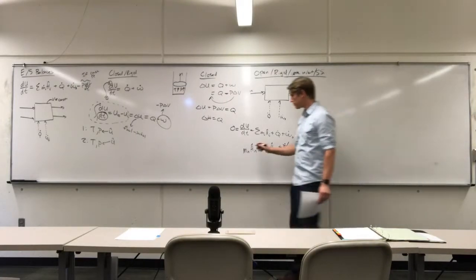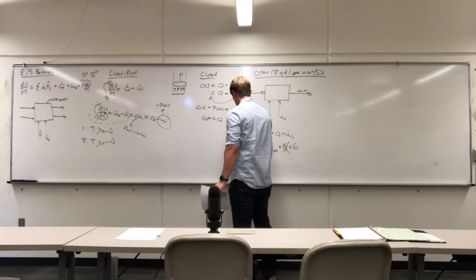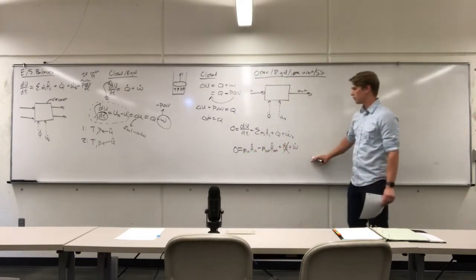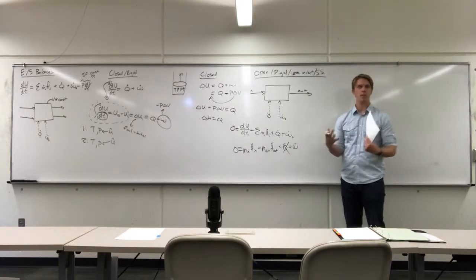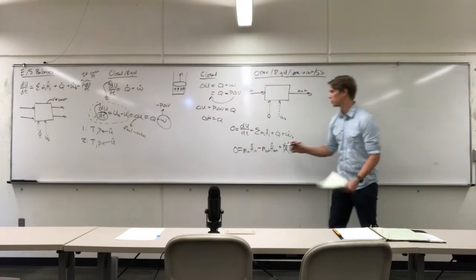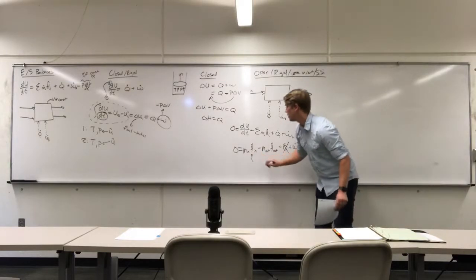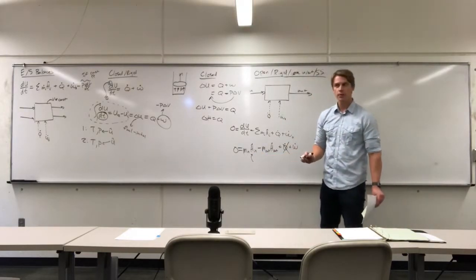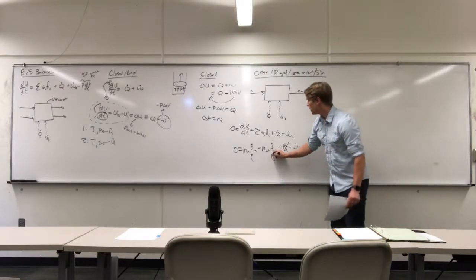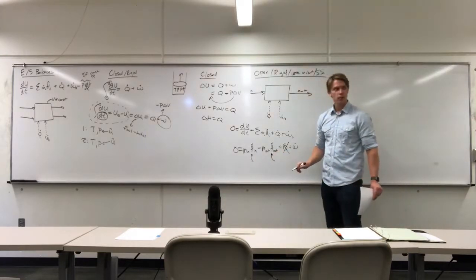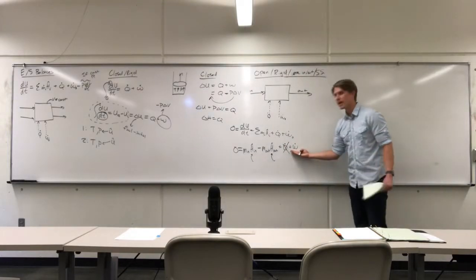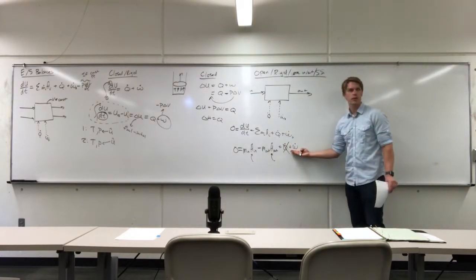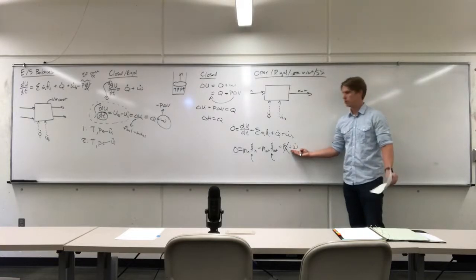Okay, so going back to the example, this is our energy balance. If we have a furnace that's producing high pressure, high temperature steam at some temperature and pressure, we can look up the enthalpy of that steam in the steam tables. We know the energy of it leaving. We can look up the enthalpy from the temperature and pressure of it leaving, and then we can directly calculate the work by manipulating this equation. Pretty straightforward, more or less just algebra, actually. Linear algebra.